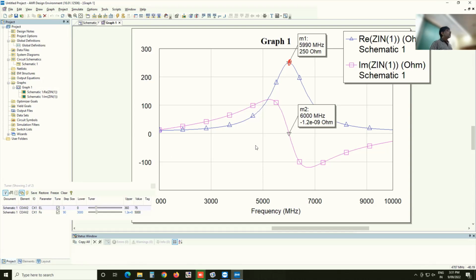But the catch is that you can only do it over a narrow range of frequencies. And this is another thing which will come over and over again: most microwave circuits have a narrow band of operation. Remember that this only looks like exactly 250 ohms at exactly this one frequency. The moment you deviate from that frequency, you start developing some imaginary parts.